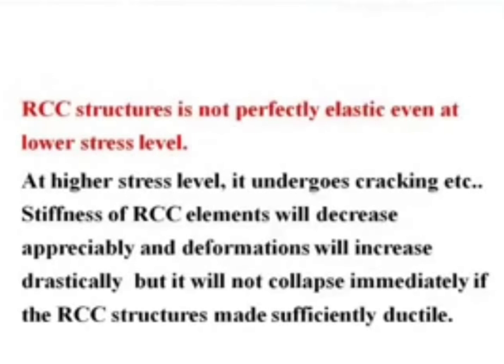So we will always try to go for the perfect analysis, but it is not always possible. At higher stress level, it undergoes cracking, etc. Stiffness of RCC elements will decrease appreciably, and deformation will increase drastically. But it will not collapse immediately if the RCC structure is made with sufficient ductility. I just now told you.